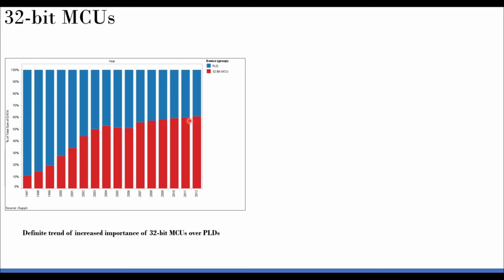And when you want higher speed, that means you need a higher number of operations per second at pretty good accuracy. In that case 32-bit is the choice for you, because with 8-bit, if you want to do some operation on 32 bits, you need to do it 4 times, right? So 4 cycles are required even for doing it using 8-bit. That is all avoided when you have a 32-bit case. Also, the higher the number of bits, the better the accuracy. Why? Because a higher number of levels, or higher resolution, is available in a 32-bit microcontroller compared to an 8-bit microcontroller.